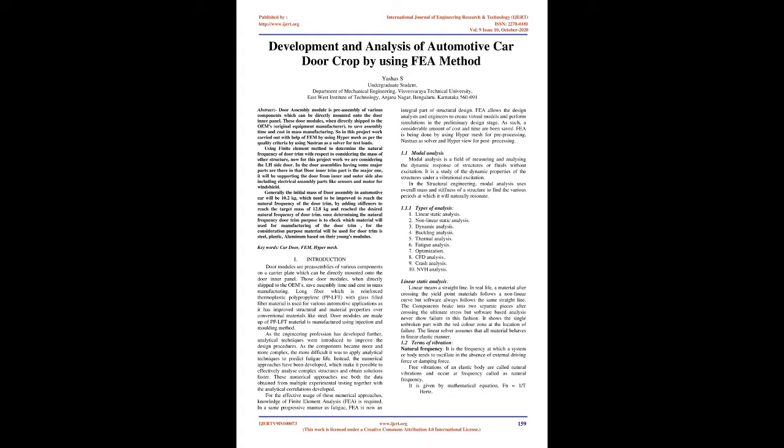Introduction. Door modules are pre-assemblies of various components on a carrier plate which can be directly mounted onto the door inner panel. Those door modules, when directly shipped to the OEMs, save assembly time and cost in mass manufacturing. Long fiber reinforced thermoplastic polypropylene, PPLFT, with glass-filled fiber material is used for various automotive applications as it has improved structural and material properties over conventional materials like steel. Door modules made of PPLFT material are manufactured using the injection molding method.